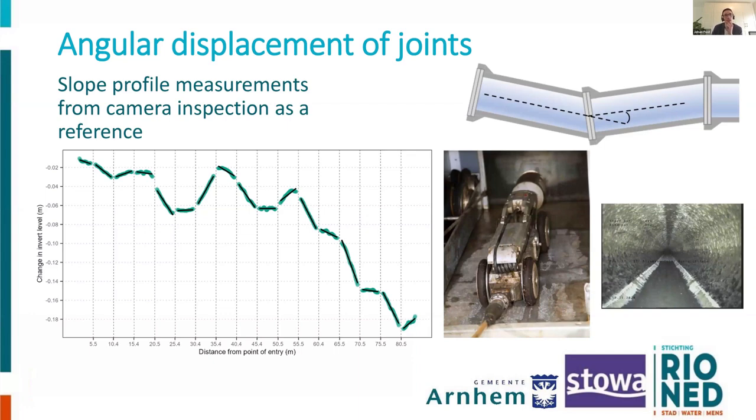Well, you see a small graph of how that looks from the camera inspection footage. A nice thing was that if you look at this pipe, asbestos cement is quite prone to leaching. Leaching means that the pipe wall can remain the same, but its structural integrity can still degrade.